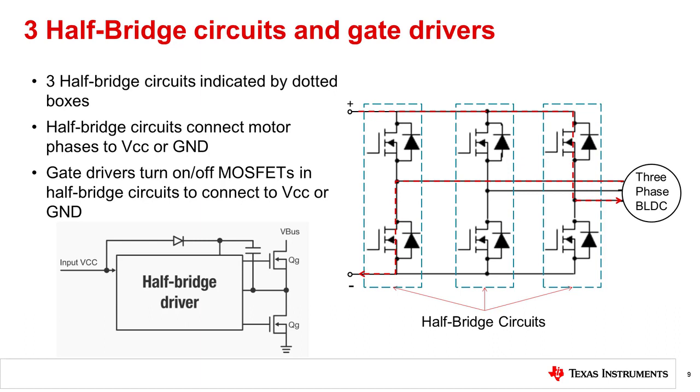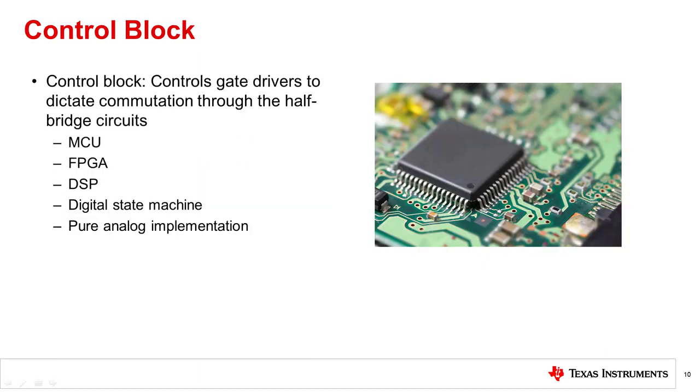Gate drivers are the circuitry connected to the gates of the MOSFETs used to turn them on and off. Motor drive devices can either integrate just gate drivers and use external half-bridge circuits, or may integrate both the gate driver circuits and the 3 half-bridge circuits. Gate drivers will be covered in greater detail in future videos in this series.